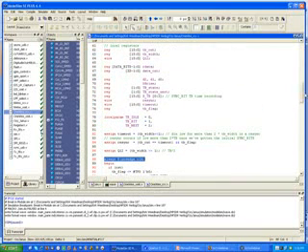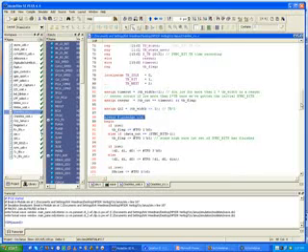So let's go back up to my local registers that I've declared, and here you'll see TB state. It's 3 bits wide, and then I have another reg called TB state next, and that's actually a combinational type output, and I'll show you how that comes into play. But anyway, the way I've written TB state, these become the outputs of 3 flip-flops that hold the current state that I'm in for my state machine.